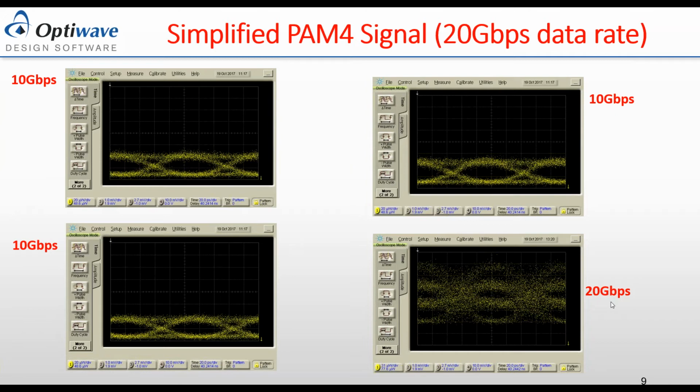Now as you see on the left side, there are two 10 gigabit inputs. If I combine them together, that one MSB drives these two laser diodes and the LSB drives the one on the right. Then I have the LSB represented by this one, the combined effect of the ones on the left gives me my MSB, and when they all go together, you get the PAM4 eye. This is a reasonable result, and this is raw data without any signal processing whatsoever.